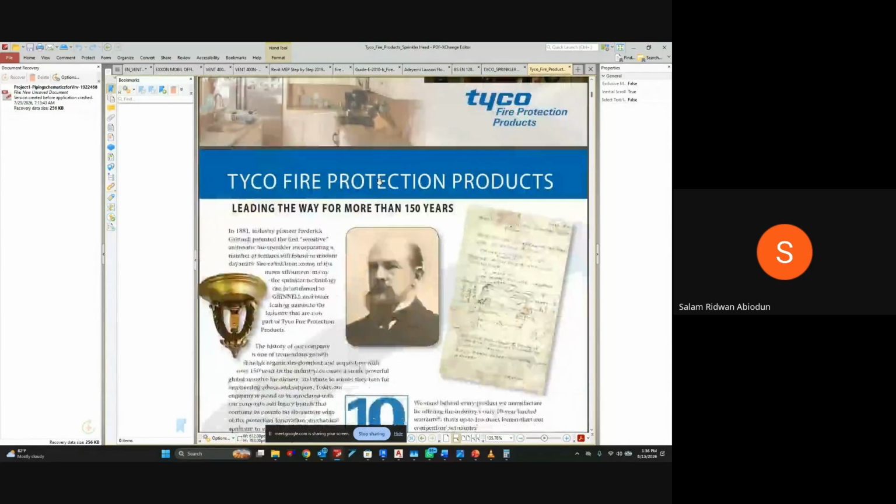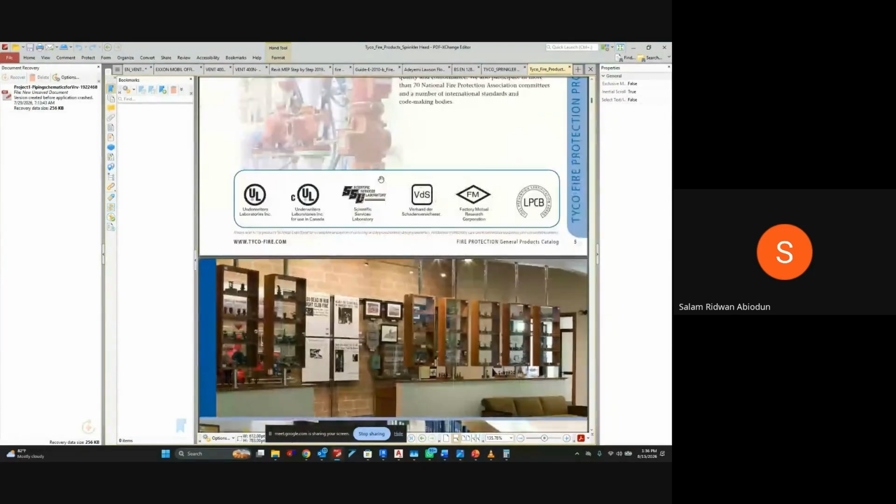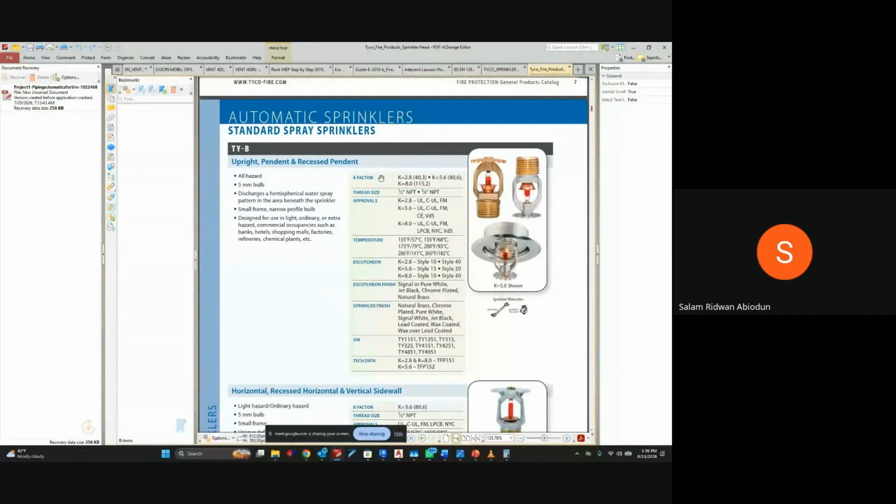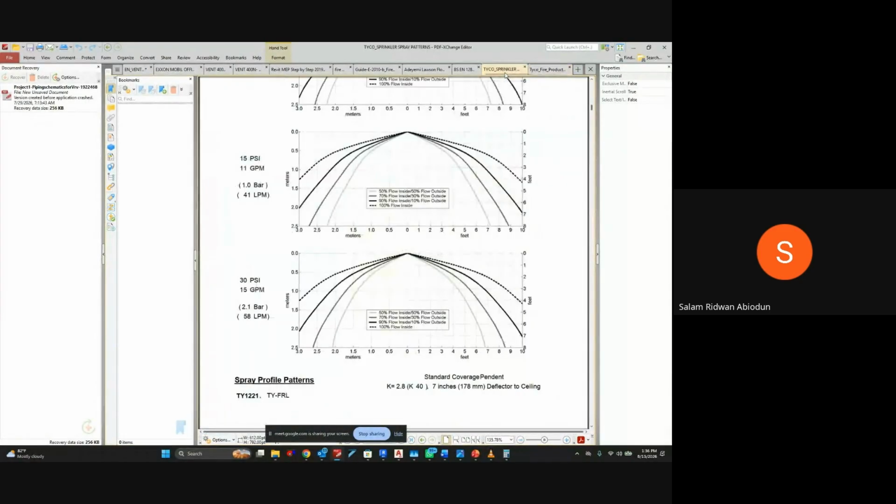So these are sprinkler heads. These are the products, so let us just go through them. To your question, you said, does the coverage differ? And I say we have two types of coverage. We have extended coverage and standard coverage. Standard coverage, when you are able to meet their minimum requirement of pressure, it will give you the discharge that you want. It will give you this discharge that they have specified here. This is their catalog. That's the spray that it is going to give you.